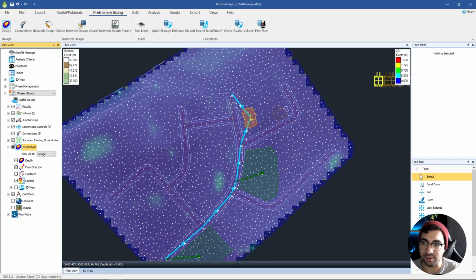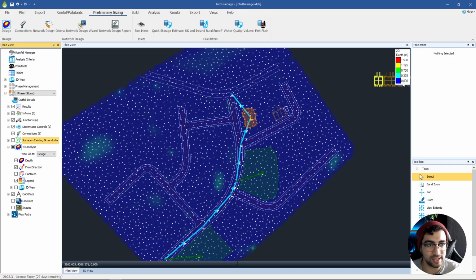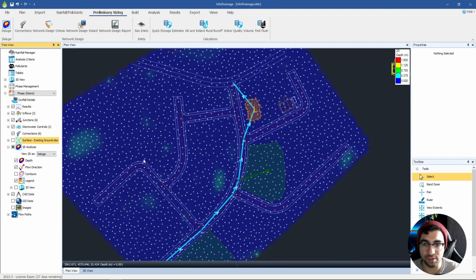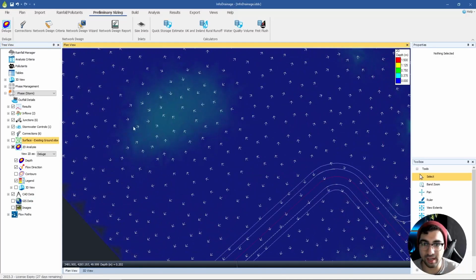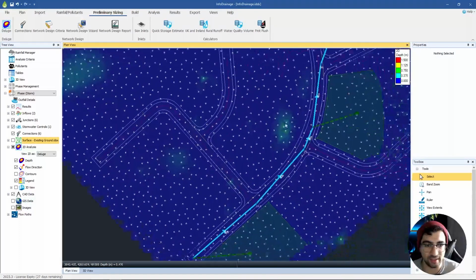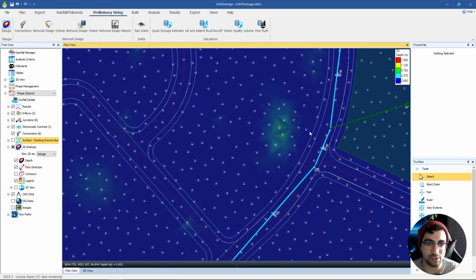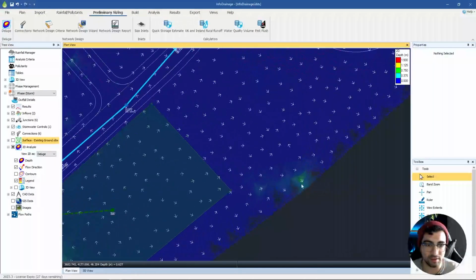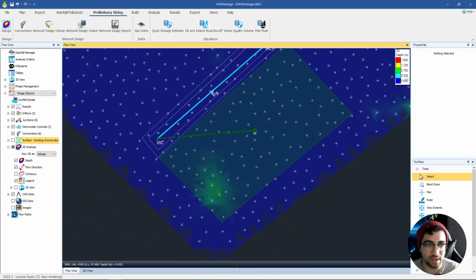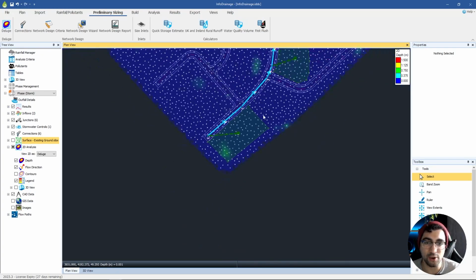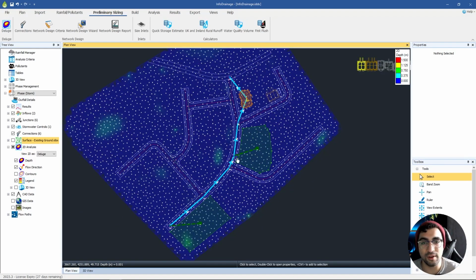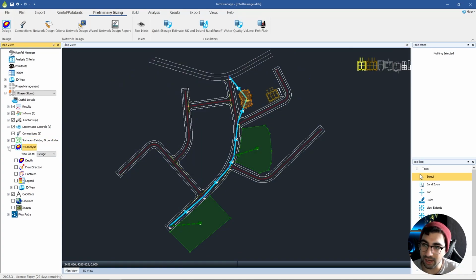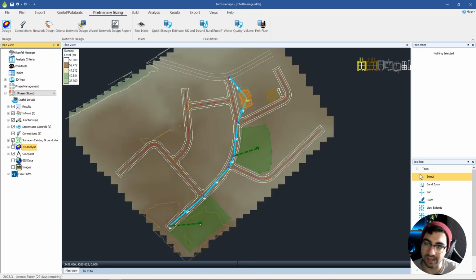you can see that wherever it is blue, let me untick the surface first so I can see better. So you can see blue is depth of 0, and then when it becomes cyan it is depth of 0.375. So that is basically where water gets concentrated. You can see even the arrows, the flow directions, point to a low spot, if you see here. So the lower the spot, the higher the depth is. So you can see on your existing surface where the water is going, and you can model it accordingly, or you want to prove something to the LLFA. We've all been there. So I'm going to tick the analysis and tick again the surfaces.